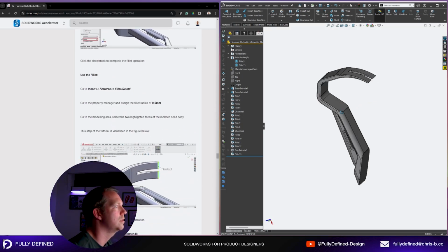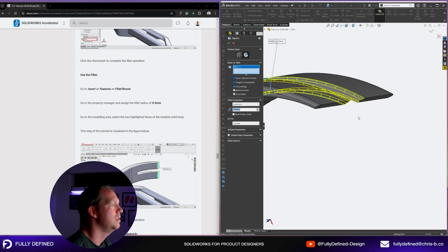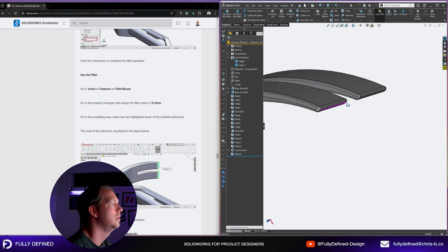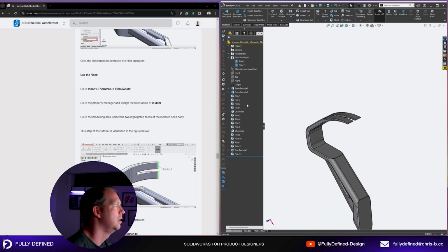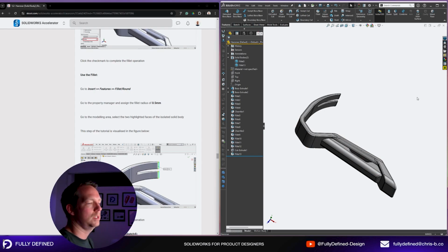More fillets, so just on the end, another 0.5. Now, because this one's 0.5, you can actually condense these fillets. You don't have to do it in 2 separate features. You can do it all in the 1 feature because it's the same dimension fillet. Okay, there's no need for a separate one there. And typically, like you can see all the features here and the fillets here in the tutorial, where you can, you want to try and minimize them. So if you've got the same fillet dimensions used in different places, if it's on the same body and it makes sense, do them at the same time.